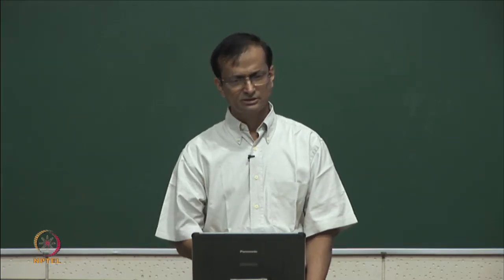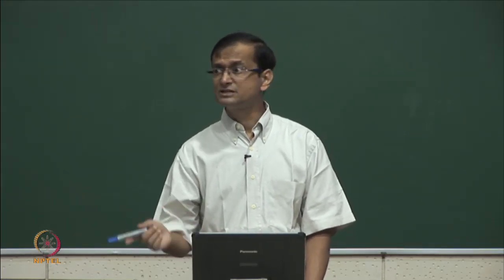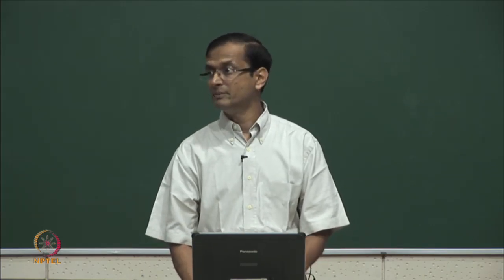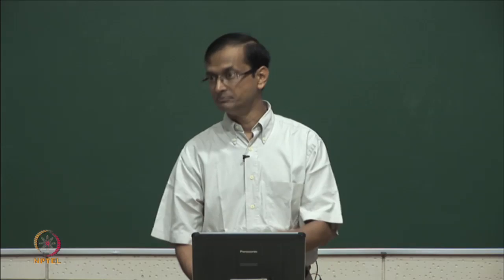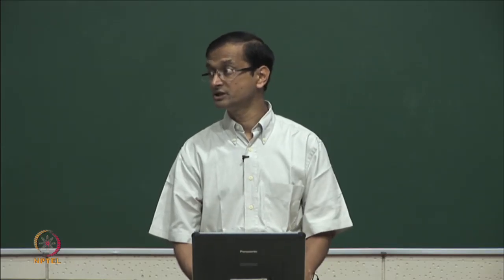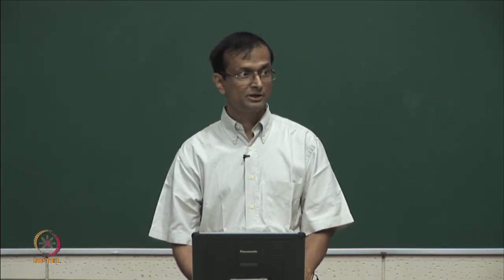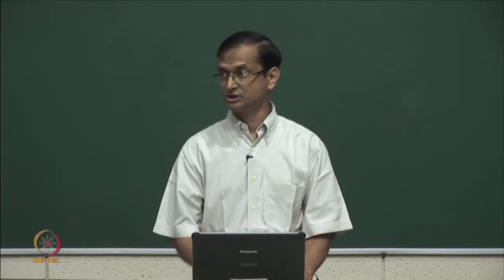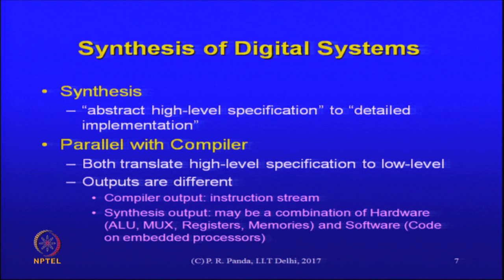But it may happen that the physical synthesis tool later on did not actually successfully manage to find a geometry that meets those timings. So, there is some uncertainty there, because of which this process may involve some iteration. You start off with the synthesis, you go through all the other steps, but at a later stage when you do timing analysis, you might actually realize that we made the wrong assumptions early on.